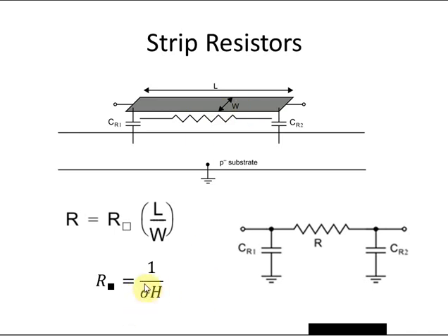So that's this constant sigma here. Sigma is a different constant depending on whether we're using copper or polysilicon or aluminum. It also depends upon the cross-sectional area of this wire, if you like, so that depends on its thickness here, denoted by the variable h. So for a given conductivity sigma and conductor thickness h, we get some resistance R sub square here.